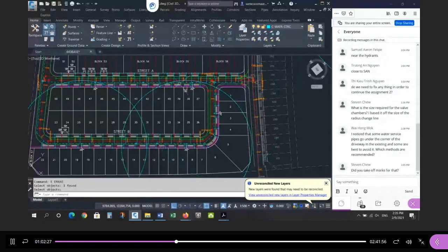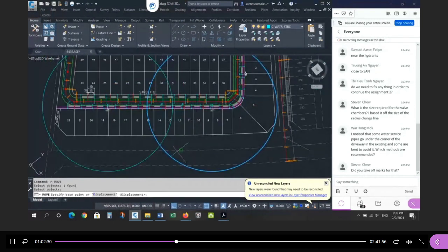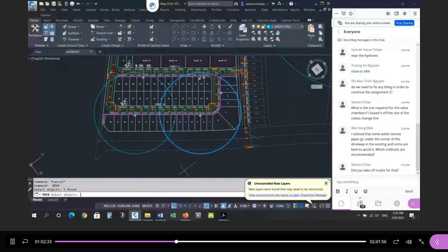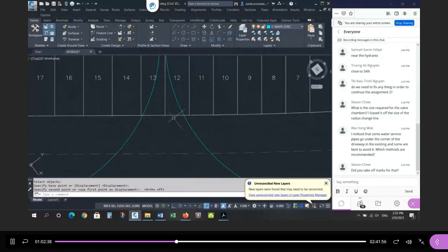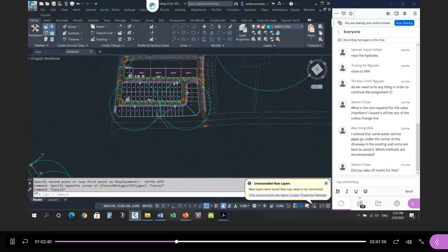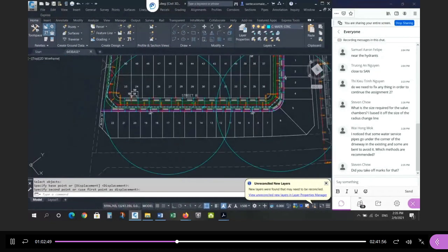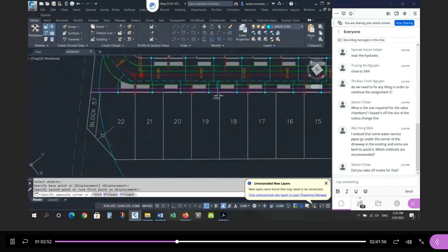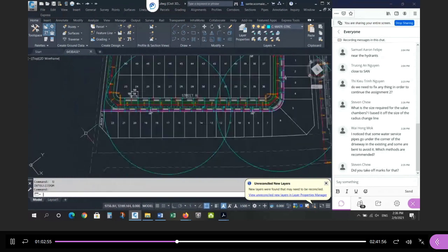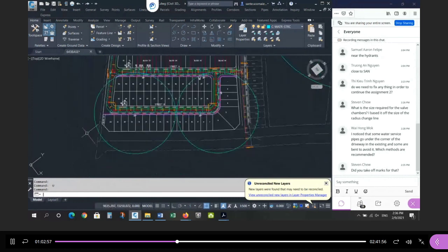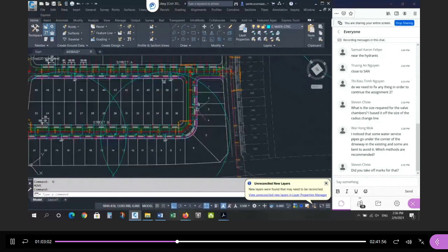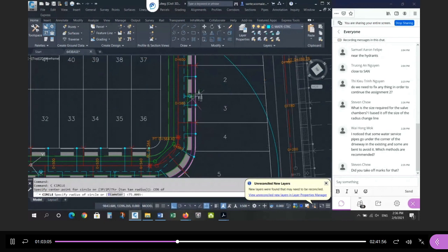If I try and move this hydrant, think about the center here, right? If I try and move this hydrant over to cover the backyard of lot 1, now I've lost coverage in the back of these two units. If I try and push this over to cover the gap here, now I'm starting to lose coverage on the road here and on this lot here. So the solution for this particular subdivision layout, the one I've provided for this year, and it changes every year, you're going to need 3 hydrants on Street B for that reason.